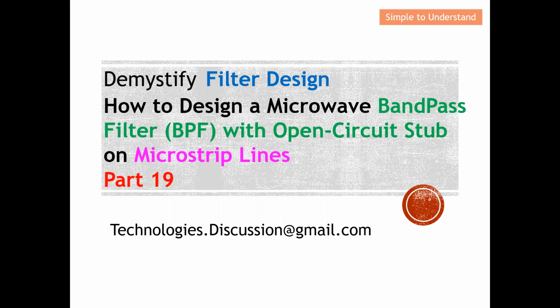In this video, I'm going to show you a quick comparison between the open circuit and the short circuit. What are the advantages and disadvantages of these two methods? With this, you have a choice whether you want to design a short circuit stub or an open circuit stub. In general, whatever I discussed in part 18 will still be relevant for this video. In fact, from the short circuit stub, I just need to do a little bit of increment, and therefore I will be able to realize a bandpass filter using an open circuit stub. This will be the part 19 series discussion on filter design.